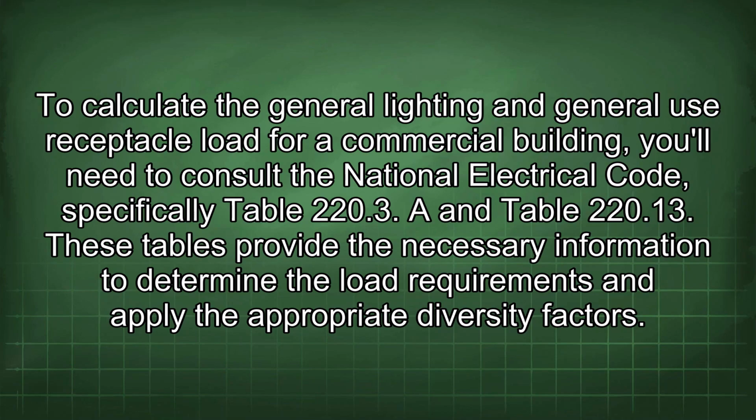To calculate the general lighting and general use receptacle load for a commercial building, you'll need to consult the National Electrical Code, specifically Table 220.3 and Table 220.13. These tables provide the necessary information to determine the load requirements and apply the appropriate diversity factors.